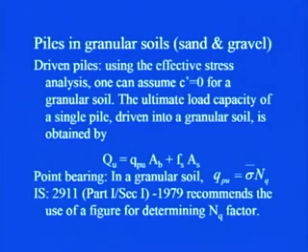granular soil. So, the ultimate load capacity of a single pile driven into the granular soil can be obtained by using this general expression, that is Qu is equal to Qpu AB plus Fs into As. So, point bearing, first let us see how we can find out this Qpu, that is point bearing unit resistance. In a granular soil, as we know, we had a general expression in which 3 terms were there, and then the last term, which we said is very small as compared to the other 2 terms.